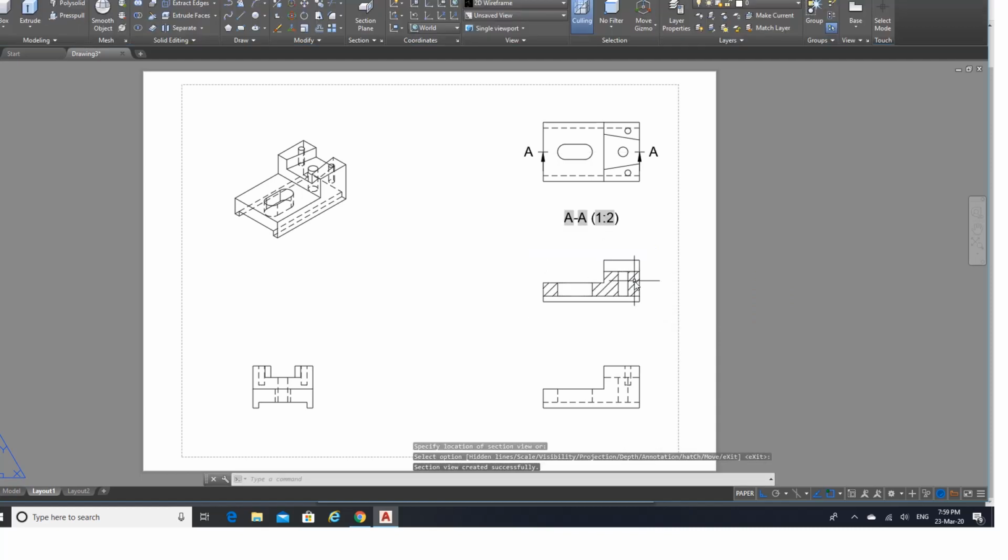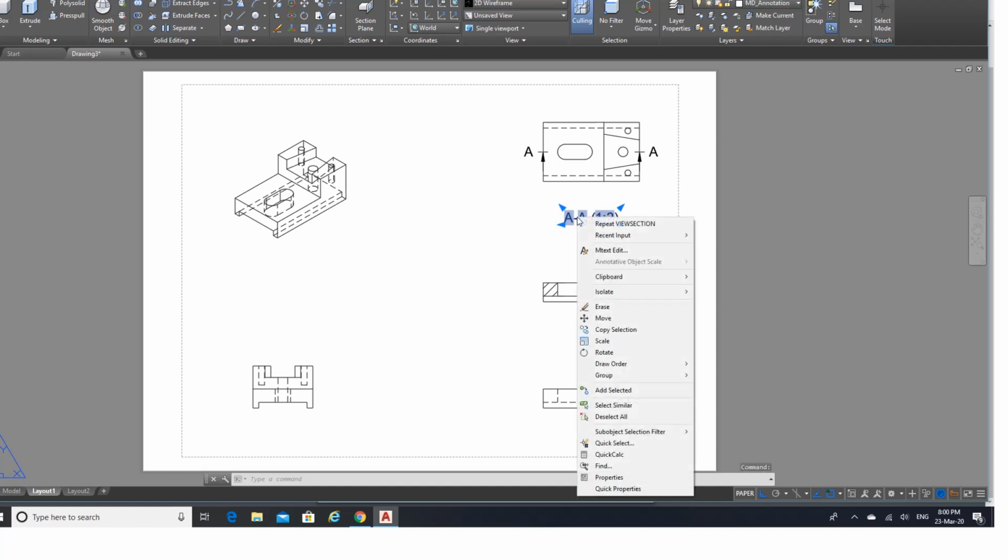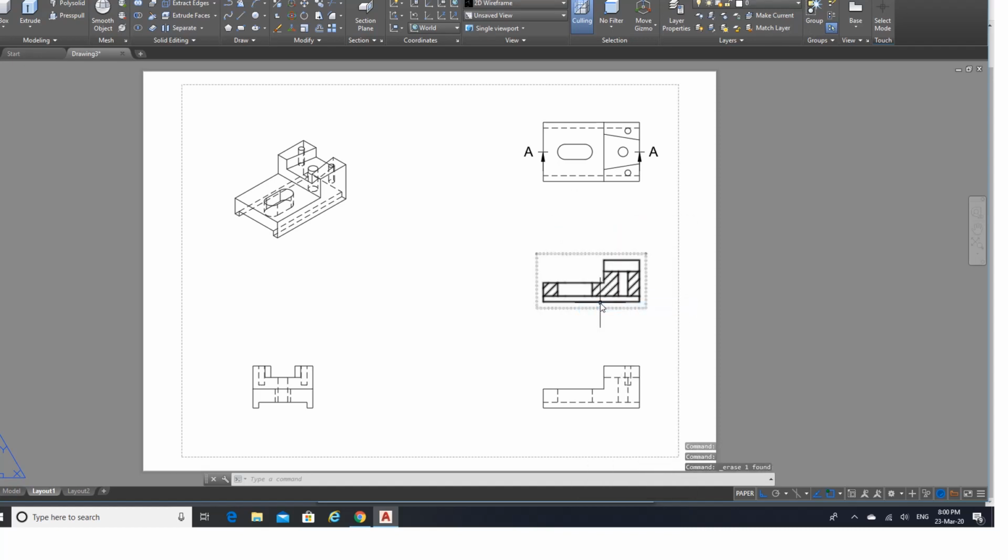Okay. See here. Now your hole is seen. See? Different holes are seen here, and then this one through hole, it is here, and then this slot is here, and in the bottom you have got this slot. Everything is there with you now. So what I need to do, click on this one, right click, get rid of this. Okay, now I need to make dimensions.